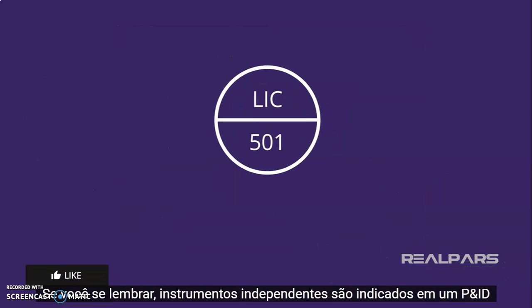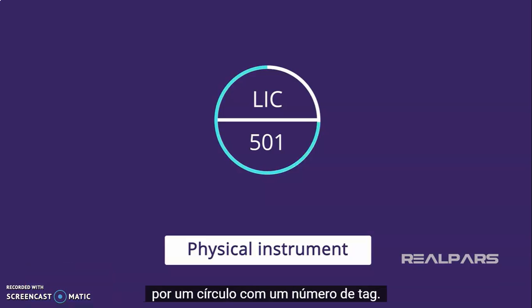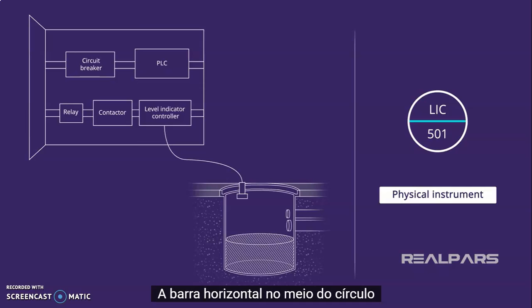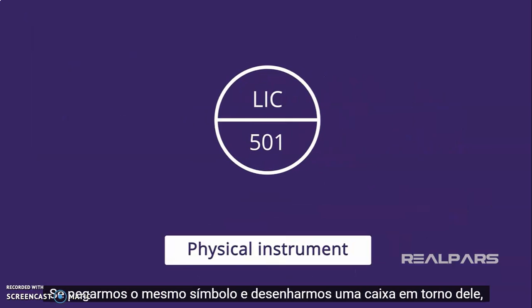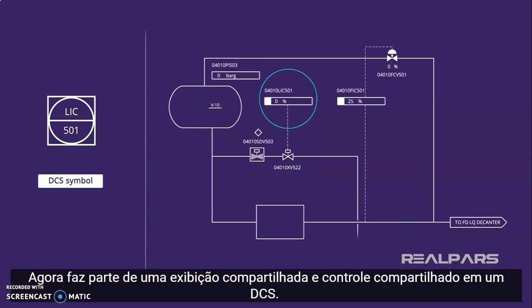If you recall, standalone instruments are indicated on a P&ID by a circle with a tag number. The horizontal bar across the middle of the circle indicates the physical instrument resides in a primary location accessible to an operator on the main control panel. If we take that same symbol and draw a box around it, it now means that it is no longer a physical instrument. It is now part of a shared display and shared control in a DCS.